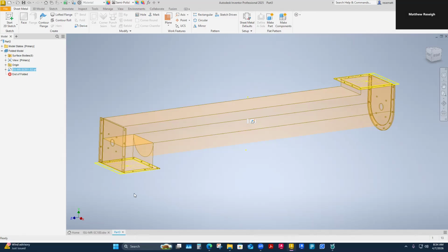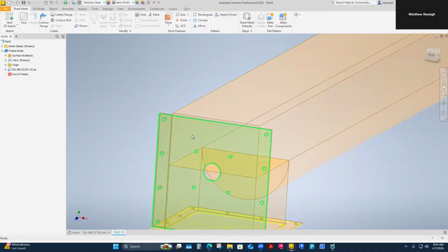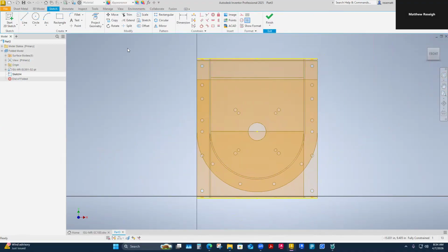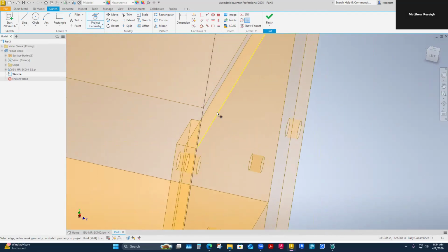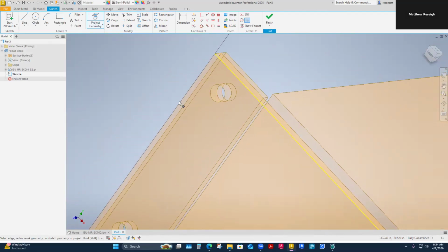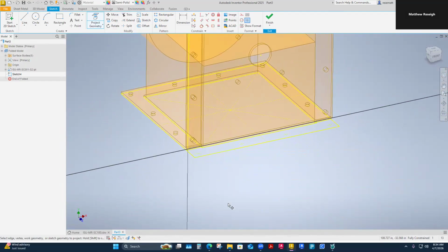So that's it. I got my sketches, got my surfaces. Let's make a quarter inch part. So I'm just going to do the end plates. I'm going to do a sketch here and project everything about this end plate over there. Same thing with that sketch on it though. I'm just keeping this sketch.